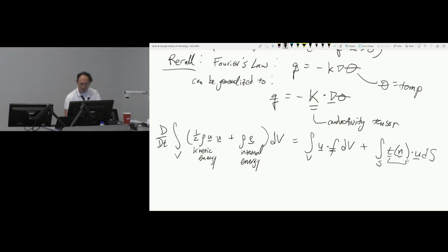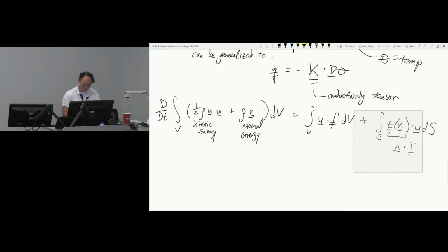And then they said, hey, we have all these divergence theorems. Having a T vector is not that useful. Let's take that information, the T vector, because we know there's 3 directions of T that depend on 3 directions of N. So let's just write that as 9 components of this basically stress tensor. And also so we can use divergence theorem, N dot T. So they put all the information in the stress vector into this tensor.